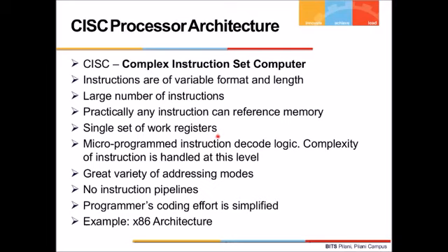Because a large number of instructions are there and they are of variable format and length, it cannot be hardwired. So we need to have a microprogram instruction decode logic. I talked about it, right? The complexity of instructions is handled at this level. There is a great variety of addressing modes, since practically any instruction can reference memory.